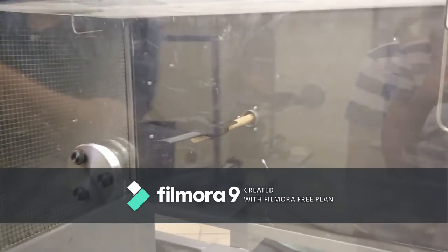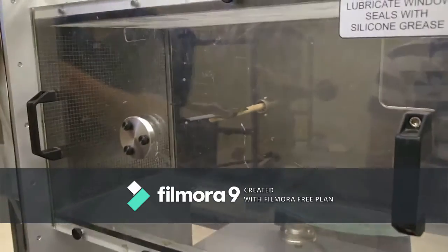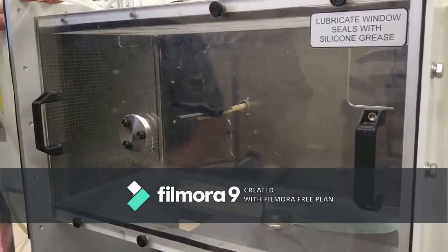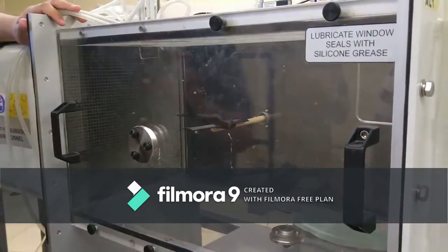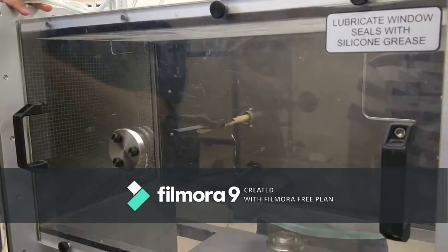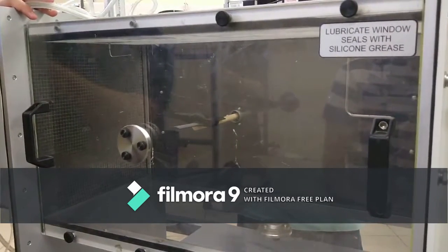When a measurement of a certain angle came to an end, the wind tunnel sometimes wasn't able to stabilize and put the forces on 0. So we had to press the reset button each time this happened and wait for it to stabilize. We saved the information that we gathered from each angle in Excel to make it easier for us to analyze the data.